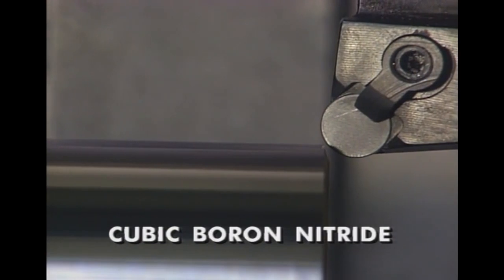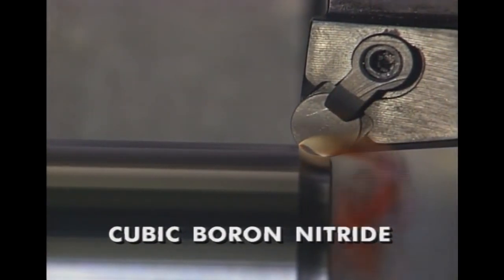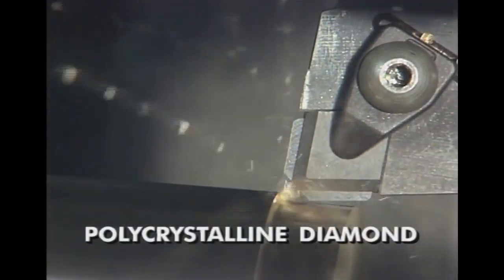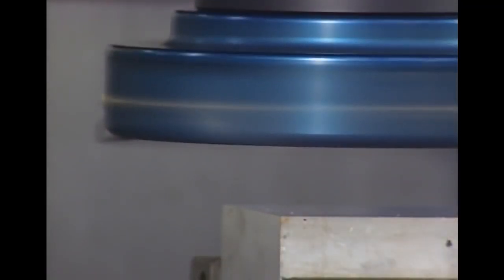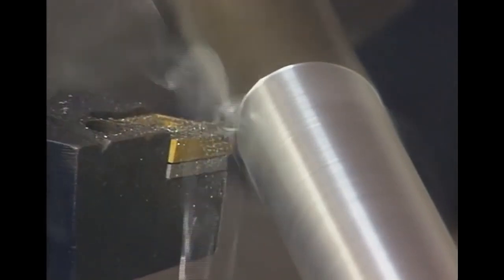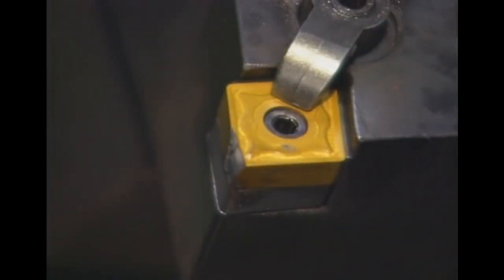The super hard materials are cubic boron nitride, CBN, for ferrous applications, and polycrystalline diamond, or PCD, for non-ferrous applications. Both materials are expensive, but can outlast carbides by 10 to 100 times. All cutting tools have a finite performance life. Then they wear out or fail. Hence, they are called perishable tools.